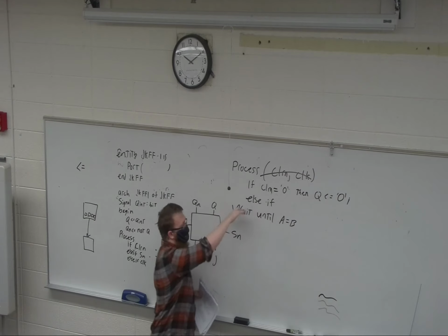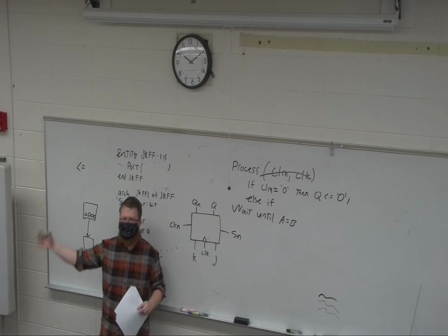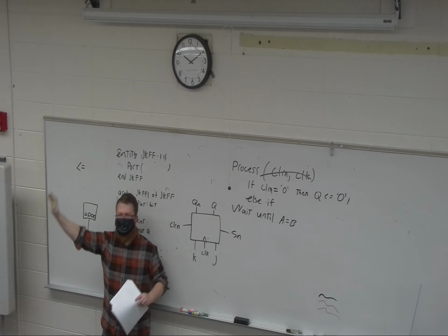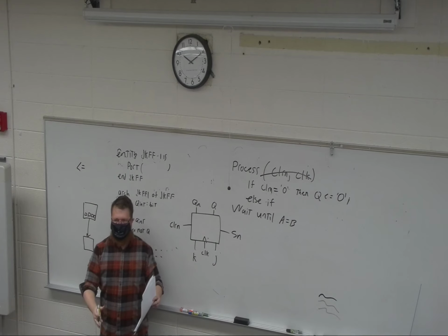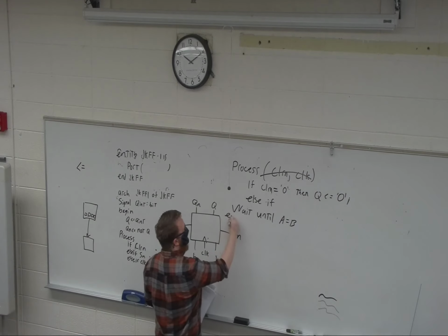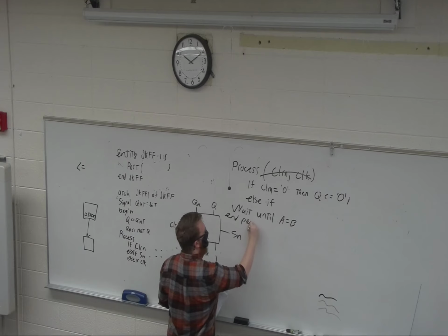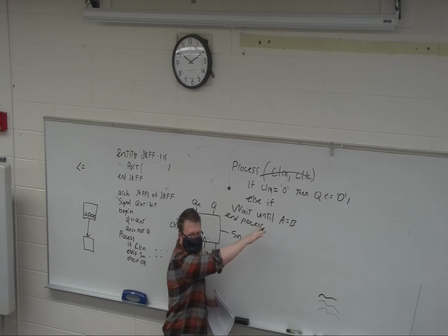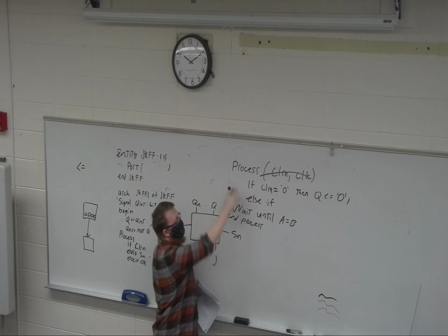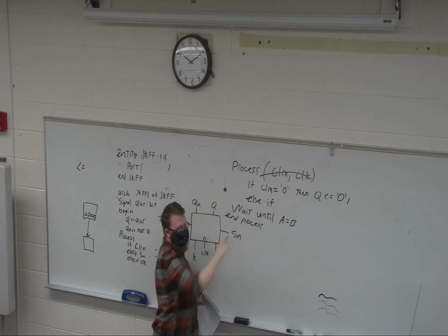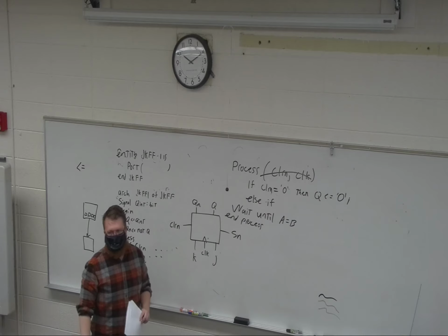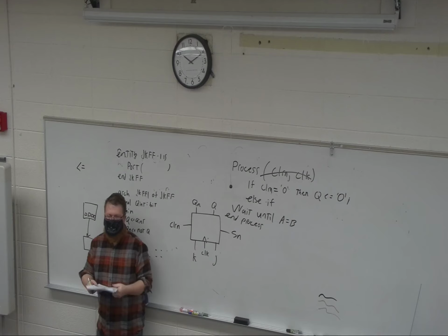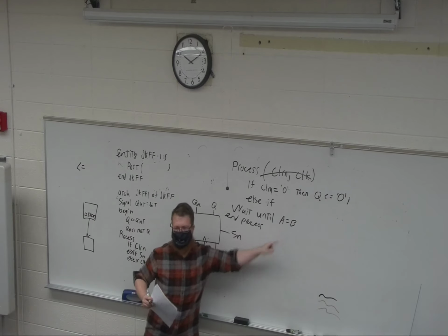And so then you'd execute through, you'd hit this and wait, and you might have some other process doing something with A and B, and it's sitting there watching it and goes, oh, now A equals B, move on with the process. And you can put that at the end of the process. And if it's just waiting there and you put a sensitivity list instead of an equality, you end up with exactly the same thing as process with that sensitivity list. So there's 2 ways to write it. I almost always use sensitivity lists. But you could see where the wait until could be useful.